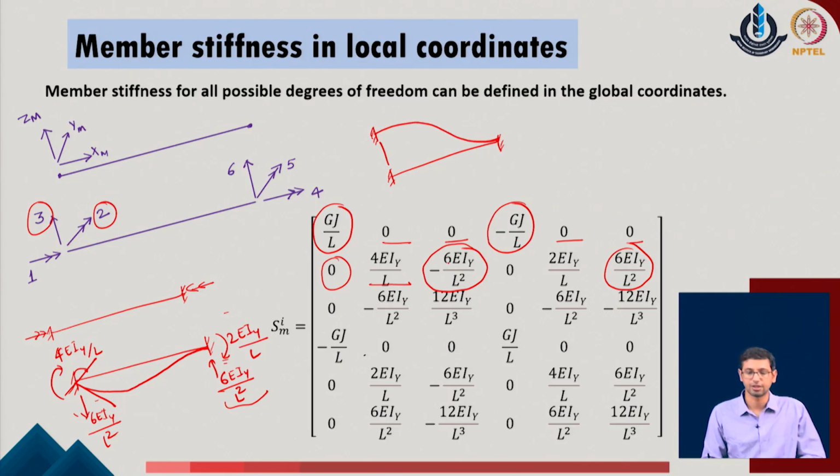This is how we define the given deflected shape, and corresponding to this deflected shape, if we get the value of the moment in the given system, we get to know that the moment directions will be like this, and the reactions will be applied in the given system in this manner. So, we got to know these values evaluated: 6 EI upon L square, 6 EI y upon L square, and the value of the reactions 12 EI y upon L cube in the given system.